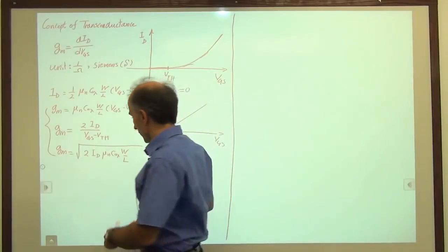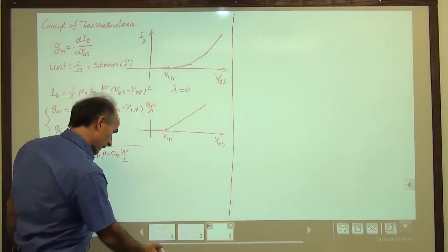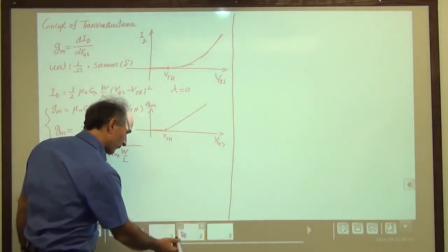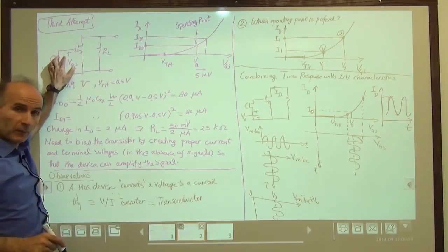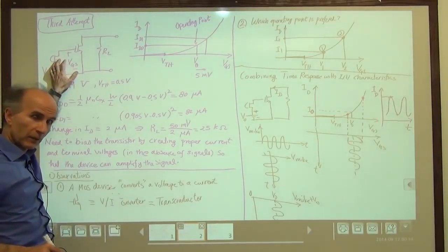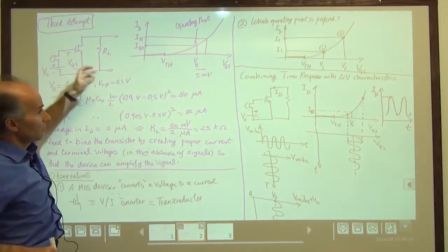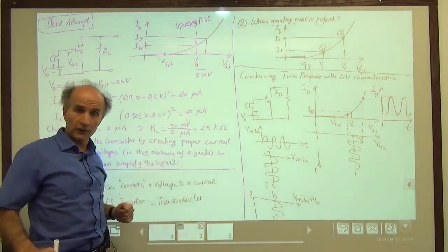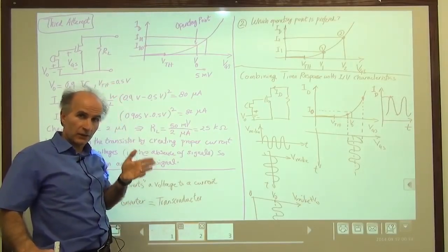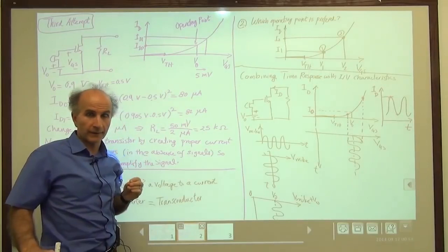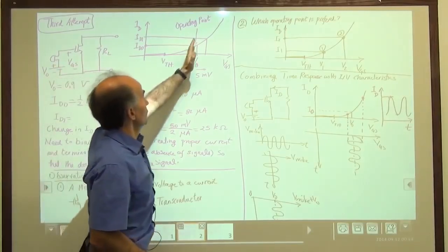Okay, our time is up. I just want to mention one more point before we go home, and that's in relation to these amplifier designs that we looked at. For example, this one, right? That was our third attempt, and we seemed sort of happy with it. We said, yeah, we have 2 microamps of change in response to 5 millivolts of change. The resistor was 25 kilo ohms. Everything looked good. But one should ask, is this configuration such that the device is in saturation? We took care of the gate source voltage, right? We applied the battery here, chose it to be this value, and so on.